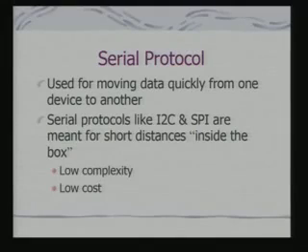The serial buses that we are now talking about are also for short distances, not really very large, and the basic idea is for moving data quickly from one device to another. The basic objective is, obviously, if you have a serial protocol, your wiring requirement is minimum.